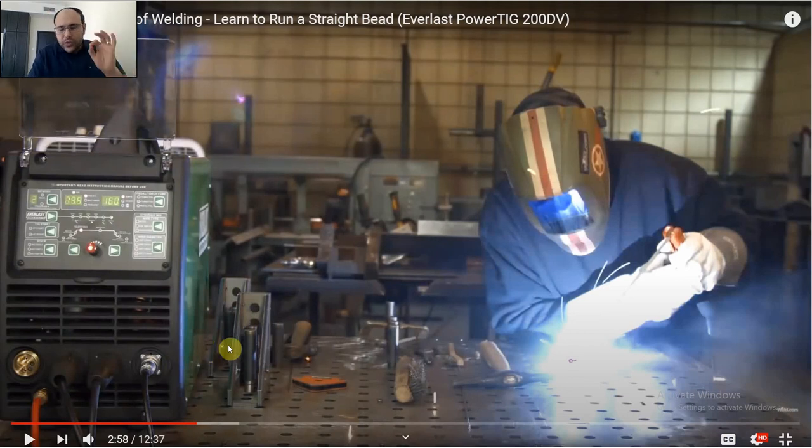The issue is that first, and this depends on the theory of arc welding that you should understand, we have to touch the surface of the workpiece with the electrode. Why? To close the circuit, to close the cycle of the electricity. As long as the electrode of this torch is away from the workpiece surface, no electricity is going through. Electrons are found at the tip of the electrode and over the surface of the workpiece. But once they touch each other, we close the circuit and allow electricity to go.